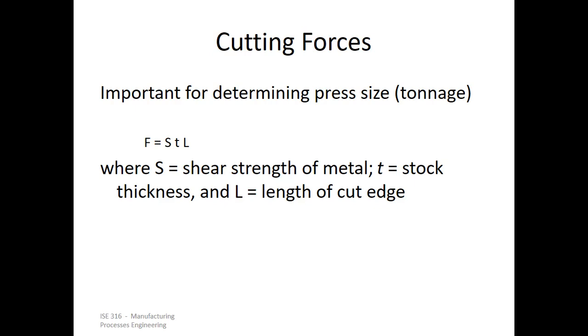It's that simple. And there is the length of the cut edge. The more the length, the more would be the area of cross section that we are shearing. So the area of shear would increase as thickness and length of cut increases. If you're looking at geometrical factors, and if you're looking at material factors, then you have the shear strength. Increase of shear strength leads to increase of force that is required to shear it off. It's a very simple formula, and that gives you the force.